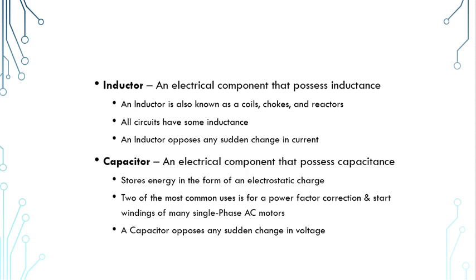So current creates magnetism. Magnetism creates current. So when we have current flowing through a conductor, it creates a magnetic field on the outside of the insulator, the flux lines, if you will. That is the reason we can use clamp-on meters, is they read that magnetic field. And that's also how an inductor stores its energy as a magnetic field. And whenever you collapse that magnetic field back into the conductor, it induces the voltage.